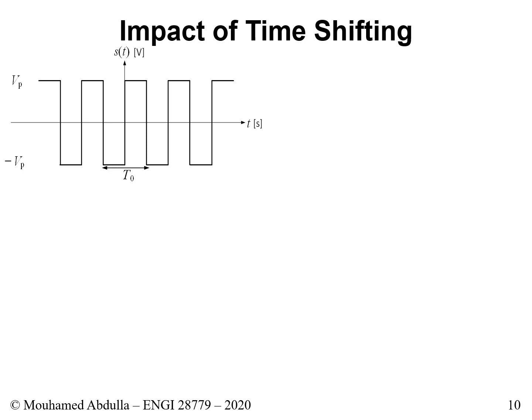Well, we're still in the time domain, and both of them were in the time domain, but over there we shifted on the amplitude. Right, so we shifted in the amplitude here. Now we want to know if we shift the signal horizontally, like this. Over there, we shifted vertically with a DC offset. Here, with the time shift, we want to shift it horizontally.